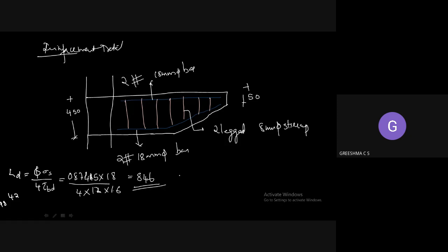Okay, so here you don't have to do the development length check. Nothing to do, just find the development length. Okay, which means that 846 mm has to be extended into the support.